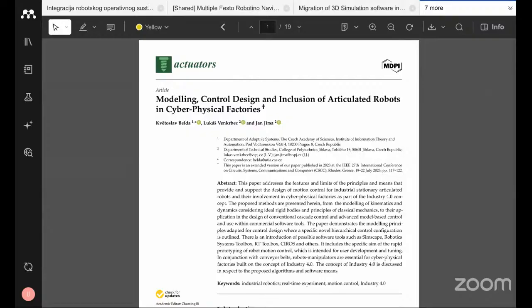So based on the joint angle, where this end effector will reach. Forward kinematics means from the angle to the end effector, right? Inverse kinematics means if you give the end effector position, based on that, calculate the angle. That is what is called inverse kinematics.